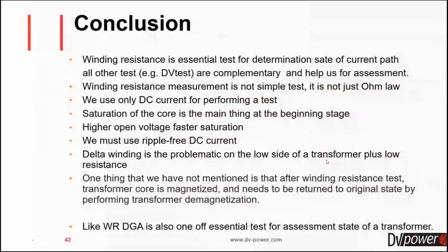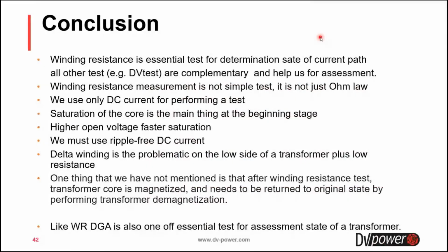This is how I prepare to talk to you, but what is the conclusion of today's webinar? Winding resistance is an essential test for determination of the state of the current path. All other tests, for example DV tests, are complementary and help us with assessments. Winding resistance measurement is not a simple test. It's not just Ohm's law.